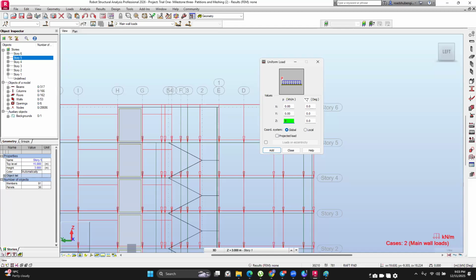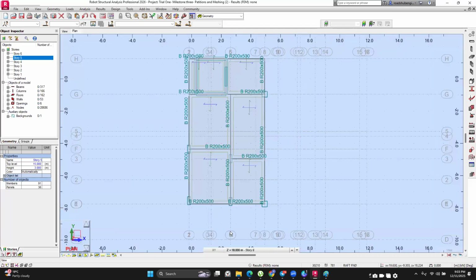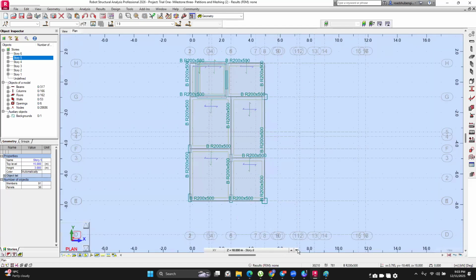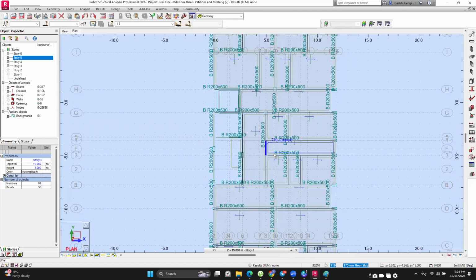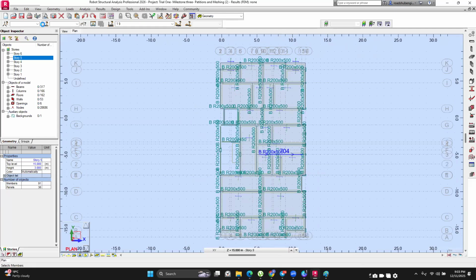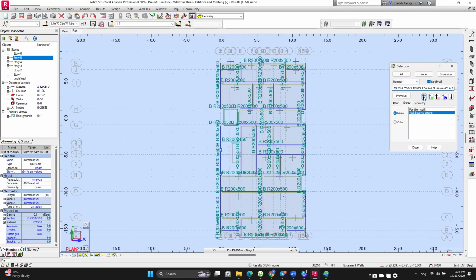For the main walls that we selected, we still have some interior walls, okay? Or let me explain before we go there. So for story number 5, let me repeat how we select them. We want to select our main wall bearing walls. So we went to member, group, wall bearing walls, clicked on the 2 arrows to select them.